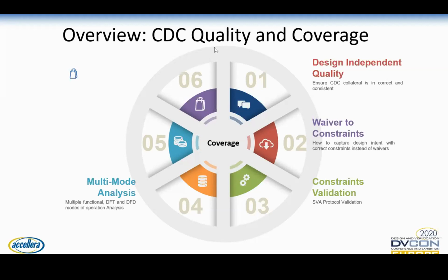The next one is the multi-mode CDC analysis. In the past, in most of our projects, we only had the functional mode of operation, wherein we do the CDC sign off in a single mode. However, our designs actually have multiple modes: the DFT modes, the TAP mode, the DFD, the visa, the bypass mode. Even in the functional modes, there are multiple modes of operation, and therein the multi-mode analysis is really an important or mandatory thing to do, so that we don't miss any coverage or any metastability issues in any mode of operation.